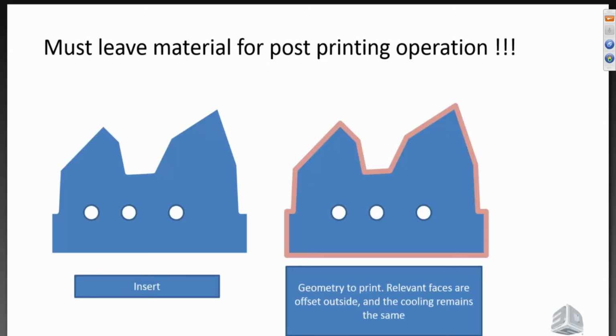Now, if you just took it to a CNC mill to rough it, you could take your finished core geometry and say, let's leave 20 thousandths, 15 thousandths, and the cutter won't go in there. Maybe we've been a little spoiled by that. That's a nice feature to have. When it comes to this, though, we're sending a 3D model to the printer. That geometry has to be on that 3D model. It's not something we can have the machine fake for us.